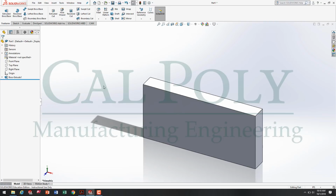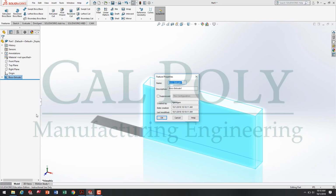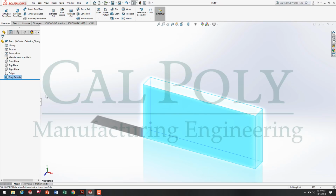This is the first feature we've created for the mill project number 1 model. In fact, if we wanted it to make sense, we could right-click over here in the Feature Manager and go to Feature Properties and write Body Extrude. What that does is it allows us to name our features and keep track of them instead of using the default SolidWorks names.